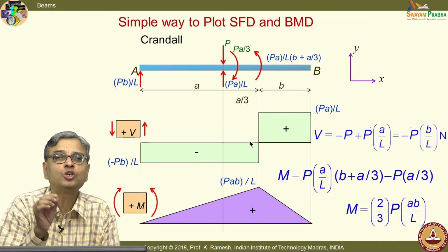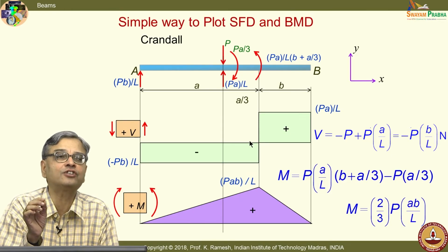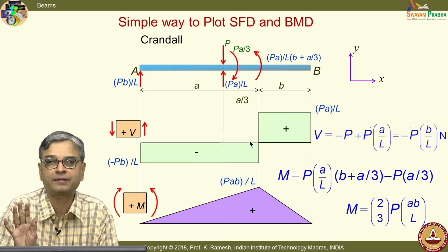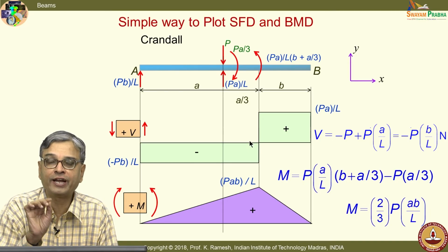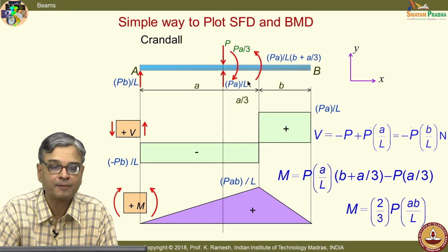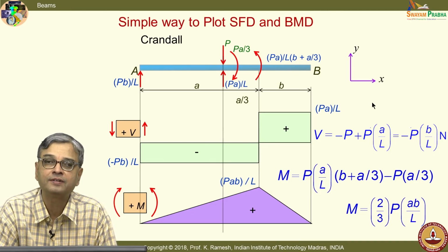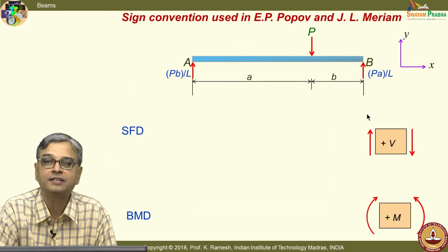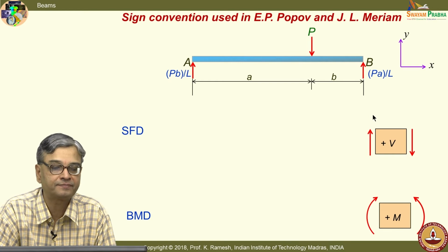So, if I move from right to left, I can keep plotting the shear force and bending moment diagram conveniently. Use this as a verification to verify your final drawing of shear force and bending moment. As far as you find these expressions, isolate the free body, draw the forces and then draw the shear force and bending moment diagram.